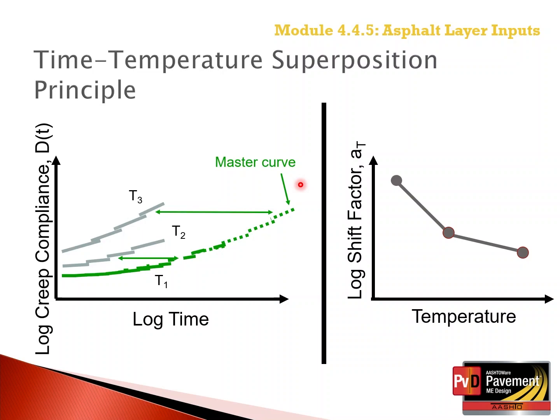So the creep compliance data measured at the higher test temperatures gets shifted to the left of the colder temperature through the shift factor function, just like for the dynamic modulus values. Use or application of the time temperature superposition principle has been checked and confirmed through many different studies and is applicable to asphalt mixtures across the typical temperature range used to test asphalt mixtures.